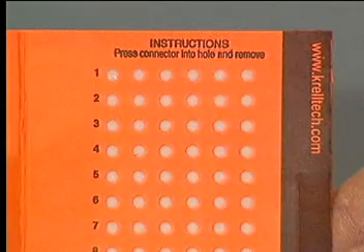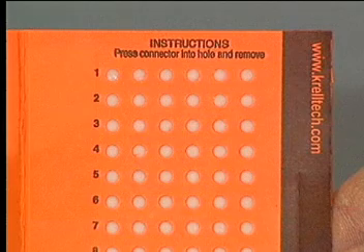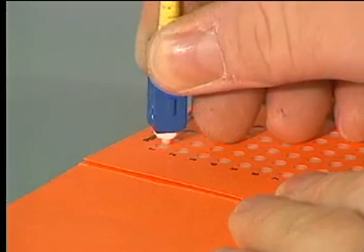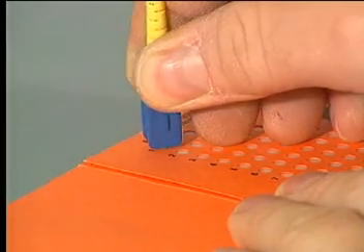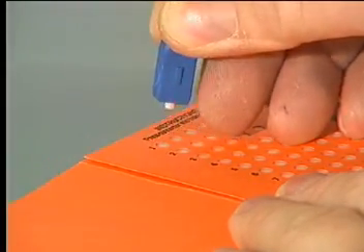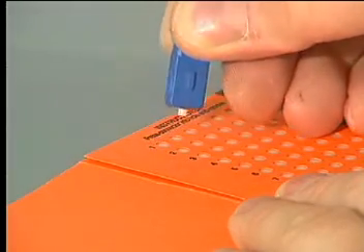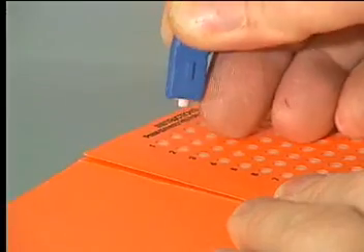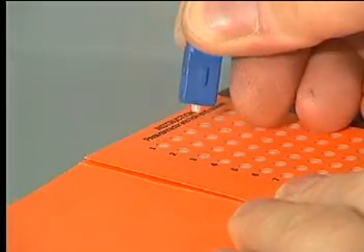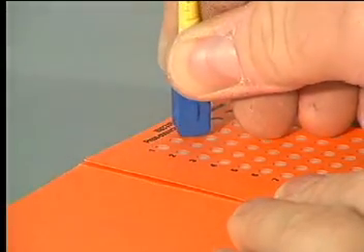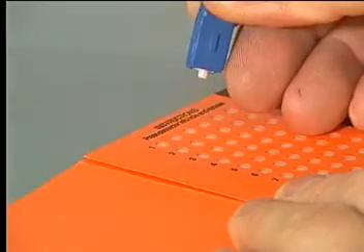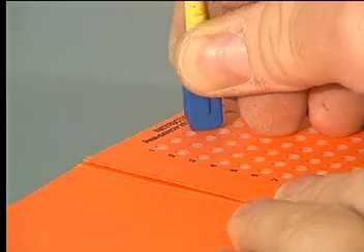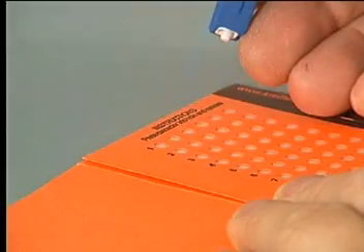This disposable pocket-sized cleaner does not require wiping of the connector ferrule, reducing the possibility of scratching. The cleaning card consists of a number of cleaning ports. The connector ferrule is simply pressed firmly to the adhesive tape in one of the ports and immediately removed. The adhesive will pull contaminants from the ferrule end. Each port is only to be used one time, and it is important not to rotate the connector while it is in contact with the cleaning port. Rotation will force adhesive to stay on the ferrule end, contaminating the connector. It could also cause scratches if abrasive grit is present.